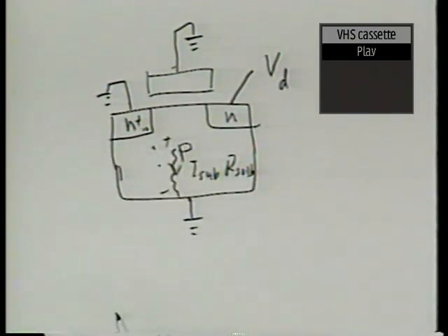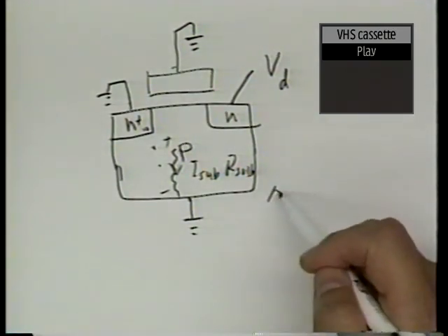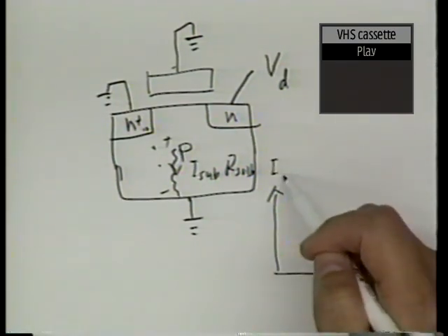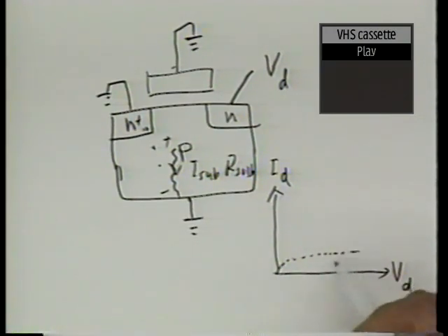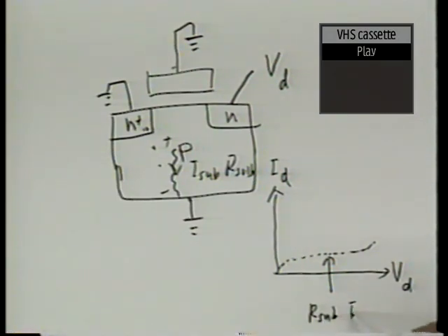When the transistor is on, it's just like opening the base. It's on, right? So the transistor will have the gain, and therefore the breakdown voltage suddenly drops to the lower value. All right. So that's what happens. So when you now look at the MOS transistor, ID versus VD, you're ramping things up to this point. All the way to this point, R_sub times I_sub is less than 0.6 volt.